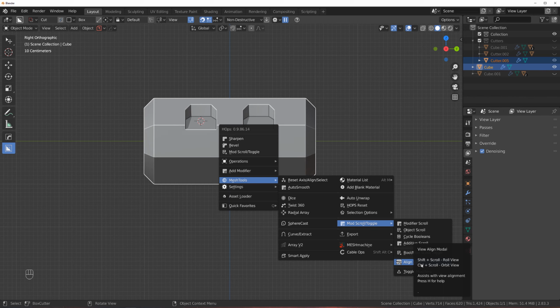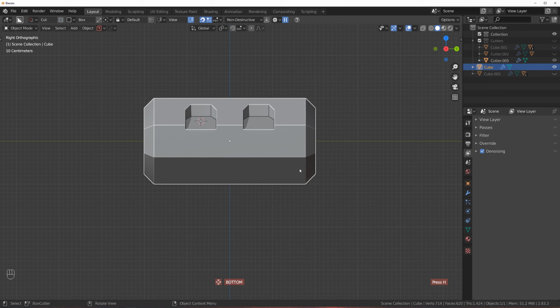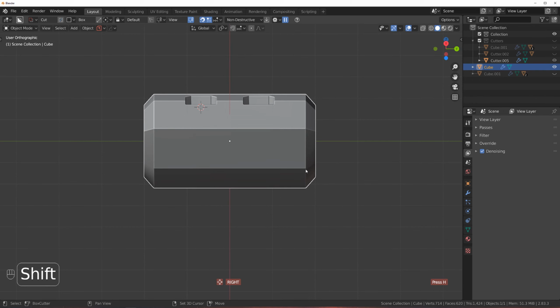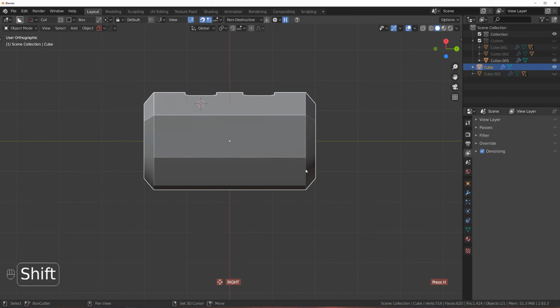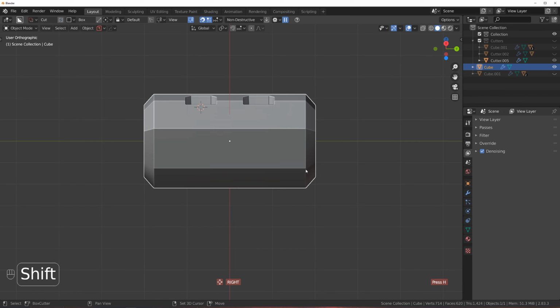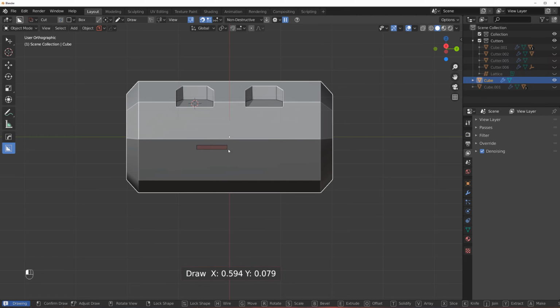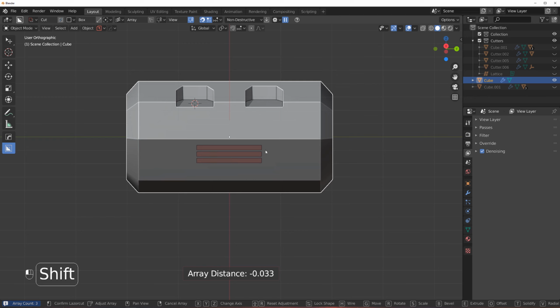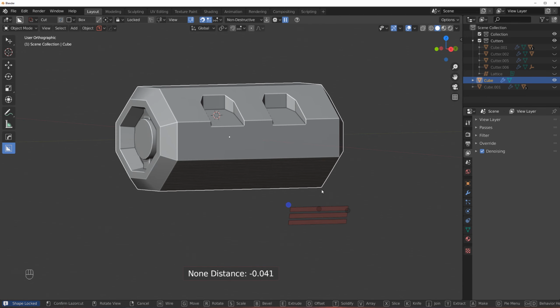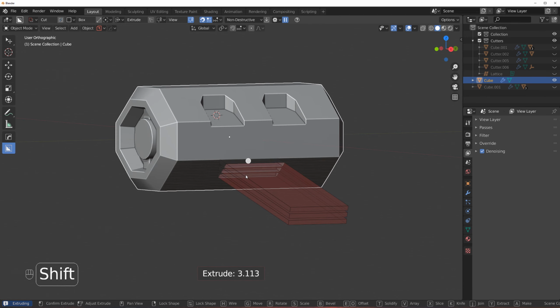I need to assign a shortcut, and let's shift and scroll down here, and maybe to this angle, and let's introduce some cuts in here like this, and press V for array, and maybe create 3 of them. Hold Shift. Now let's drag them in. That will do.